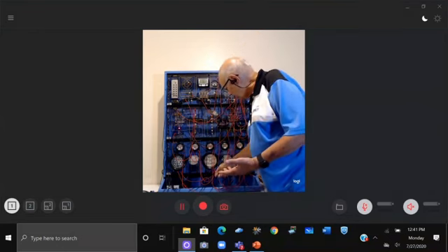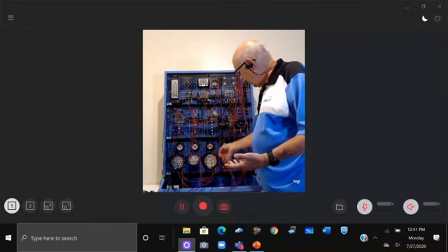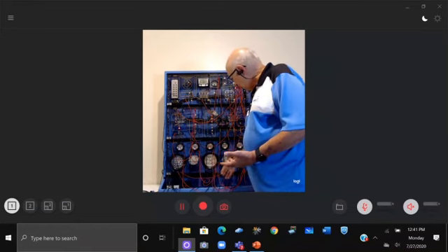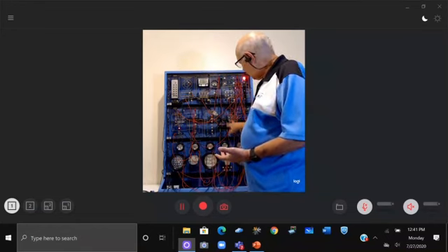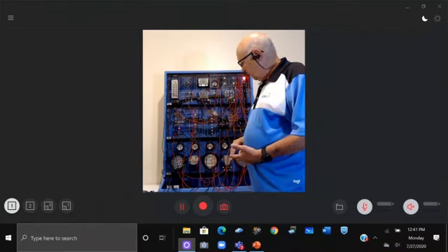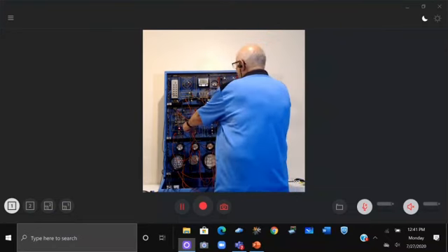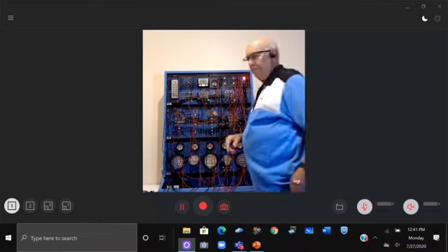Okay, here's the backup light. Does it have power? Yes. Does it have ground? Yes. So then the thing about it is it must not be getting a signal into the output module. This is a good time to also identify why these two modules have lights on.